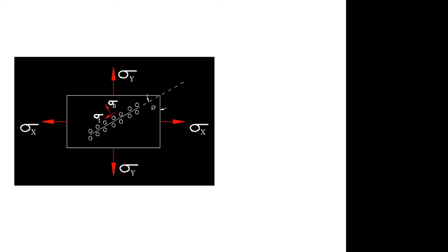So in neither direction have you exceeded 100, right? Along one direction it is 70 and along the other direction it is 50. In neither direction has it crossed 100, but there is a possibility that due to the combination of these two normal stresses, in some other plane there may be a stress which may exceed 100 units of stress normally, say along some oblique plane like this.